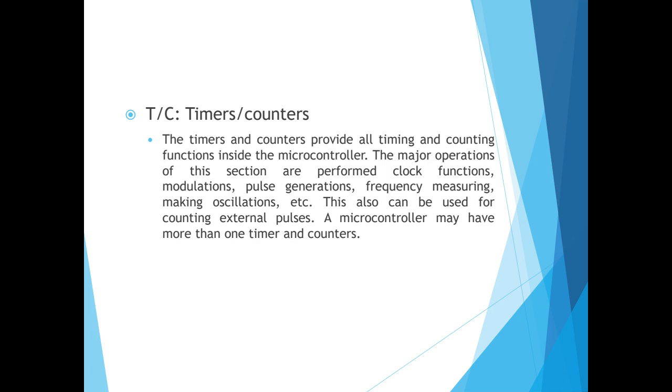One of the components of the microcontroller is called the timer counter. This component provides all timing and counting functions inside the microcontroller, and the major operations of this section are clock functions, modulations, pulse generators, frequency measuring, making oscillations, and so on. It can be used for counting external pulses too.